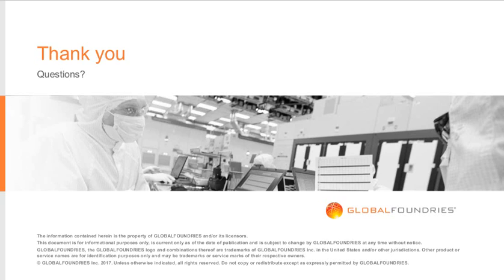For the PA design, we care more about the drain to source breakdown. For the switch design, the gate breakdown may also be a very important one. And for that one, the gate breakdown, we put low. That's why we also put a high density resistor. This high density resistor can be helpful for the switch design isolation.